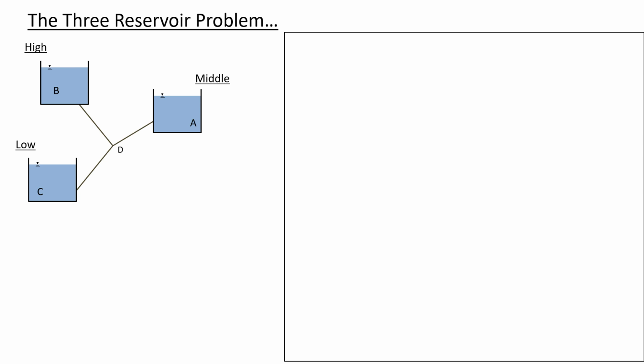Think about a horizontal pipe. If you've got a horizontal pipe and we're connecting it to a reservoir and the two water surface elevations are the same, there's not going to be any flow between the two reservoirs if the two elevations are the same. But now, what if the water level is low on this side? If the water level is low on one side, then the water is going to flow from where the energy is high to where the energy is low. So the same thing is true in this whole analysis.